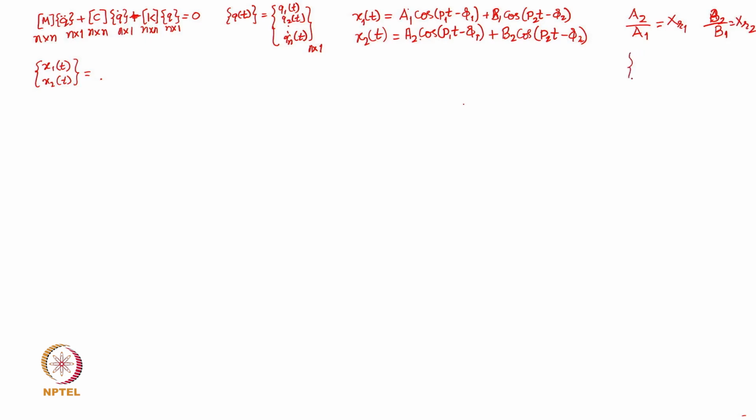So, if we now see this in one specific case of a 2 mass system where the degrees of freedom were 2, and their numeric values were such that the mode shape was 1, 1, then that actually means that a2 by a1 was 1 for the p1 mode, and b2 upon b1 for the second natural frequency was minus 1.